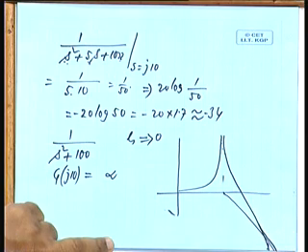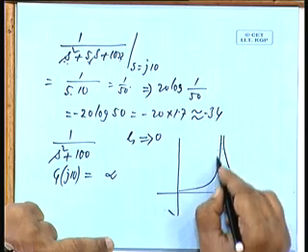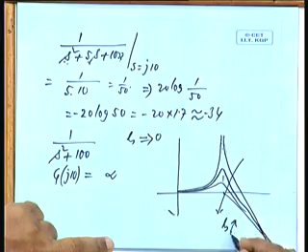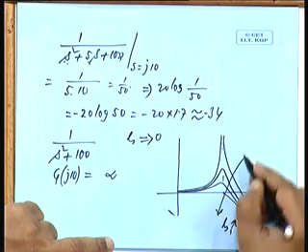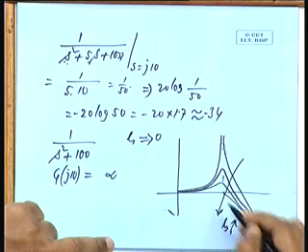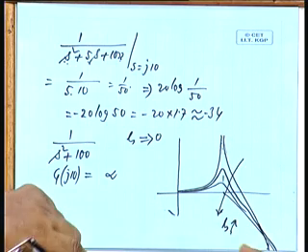The slope will finally be 40 dB per decade, tending to infinity and then coming down again from there. So, as I keep on increasing zeta, this will keep on falling like this. This is zeta increasing, a simple way of giving the symbols. This is the direction the curve tends toward as zeta increases.